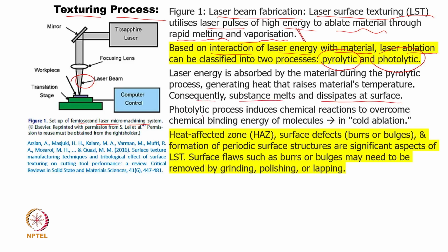Coming to the photoelectric process, only the chemical energy that is really required will be overcome. Maybe only the breaking of the bonds is required, and that is why this process is also called cold ablation. We are not raising the temperature to a significant extent, we are not really melting, we are just debonding the chemicals, and then we are removing the material from there.